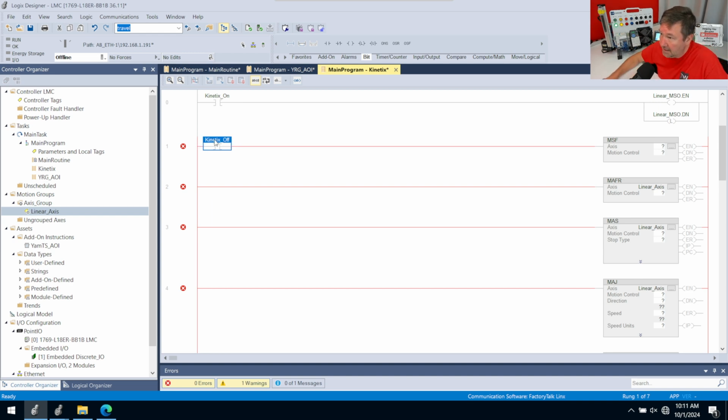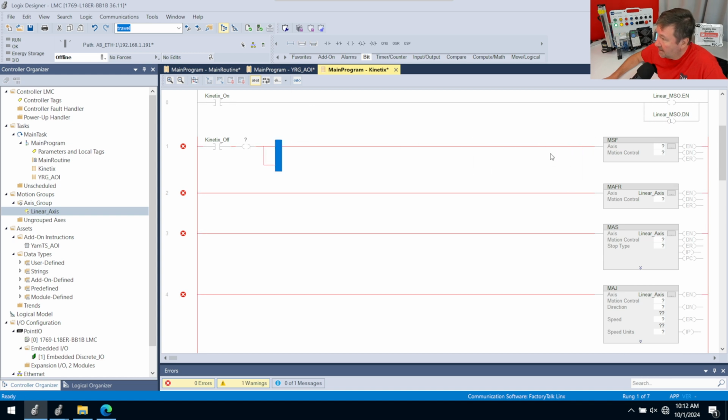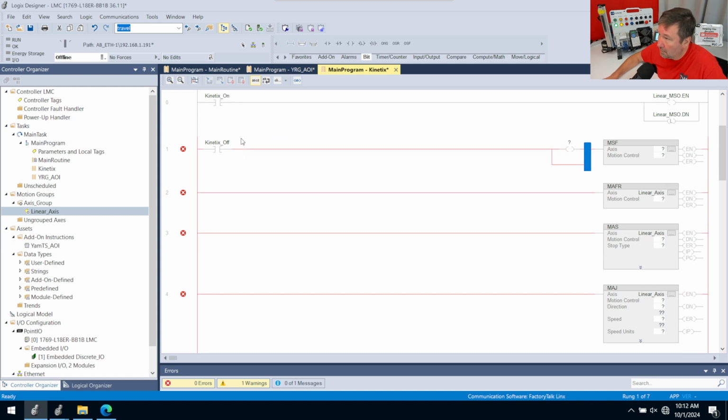And let's right click it, new, create. And then let's bring down an output energize. And we'll go ahead and drag our branch down because we're doing the exact same thing we did up here. Drag over it and drag a latch down. And then, well, I mean, arguably, yeah. Well, first we need a tag. So let's call this one our linear MSF.